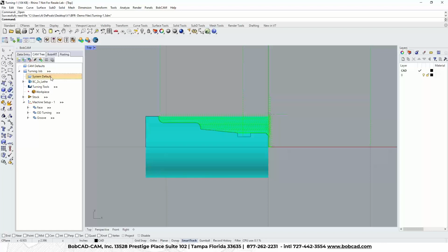So that way, when you're in the software, common features are going to come right up or defaulted to your preference. Okay. When we look at the BC2X, this is your machine definition. This handles the kinematics of the machine, you know, limits, direction of cut, things like that. As far as specifically with the machine definition, okay, this is your post processor. So this is what formats your code.